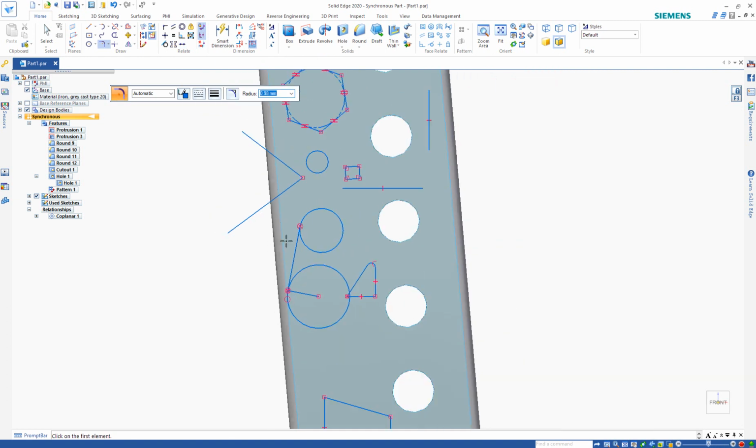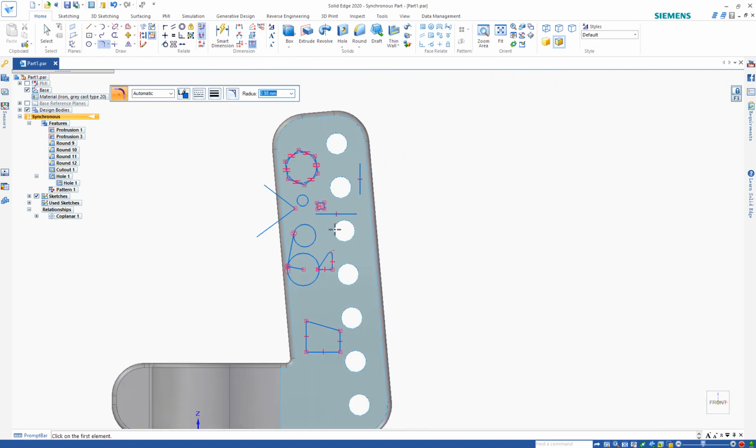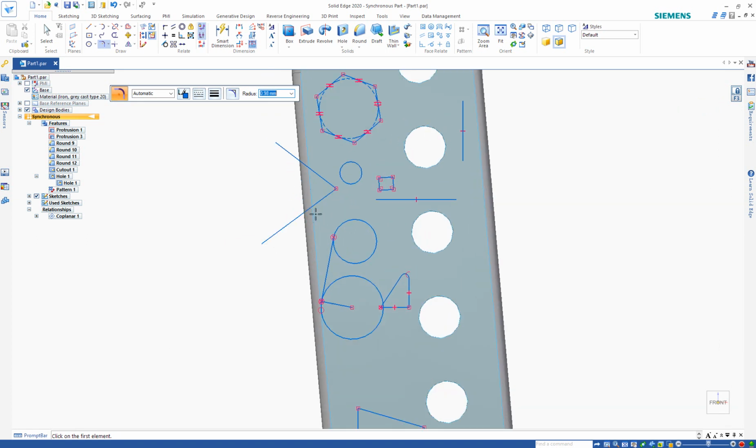And this is the tool that you can use to make your sketch. Once the sketch is done, the purpose of sketching is to generate a certain shape of area to extrude or revolve. We call it regions. And in Solid Edge, like I said before, the difference is that the boundary of the region can be two things. First, it could be the drawing that you made as you can find in other software, or it could be the edge of a